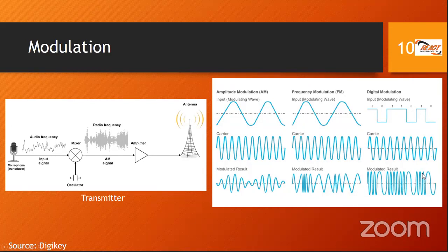So this is just a visual representation, all to say that we have a frequency that is generated on our radio, and our voice, or whatever signal we input, modulates that frequency to end up with the frequency that is eventually sent out via the antenna. So bear in mind, we have to modulate that frequency to impart the information on it so that it can go over the airways, so that somebody could receive that signal and extract that intelligence or information. It could be voice, or it could be a digital signal.